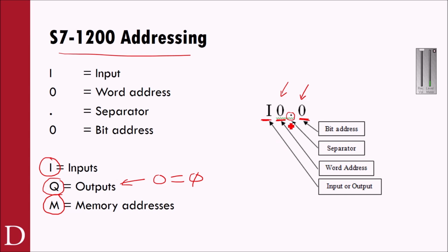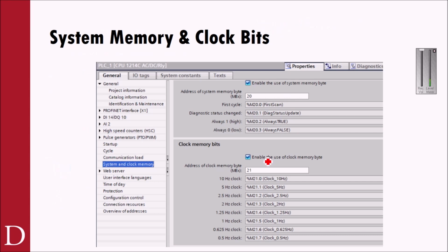So right, wrong, and different. In the world of Allen Bradley, we used I:1/0. One of the things I didn't like about that was they used that slash in a compute instruction. You can't use it for the divide, right? So you have to use the straight vertical for divide in Allen Bradley. So I do actually kind of like using the dot to signify the separator between the word and the bit.